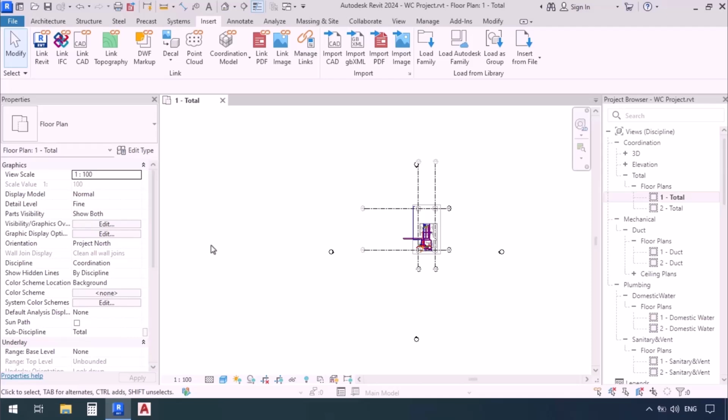When it comes to creating schedules, you'll have to pay attention to several things. You see, we can only create schedules of the items that already have been modeled. So if there are any items that you haven't modeled in your plans, naturally you won't be able to create schedules of them. So there can only be schedules created according to the LOD. So when it comes to signing a contract, remember a couple of things, most important of which is that they don't require a low LOD from you, but then ask for all of the details mentioned in the project. So now we will begin scheduling the ducts.